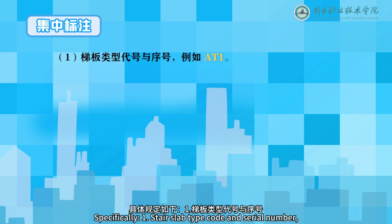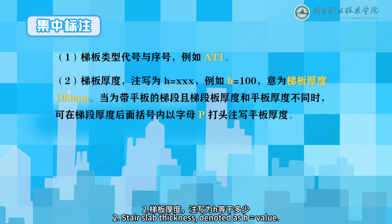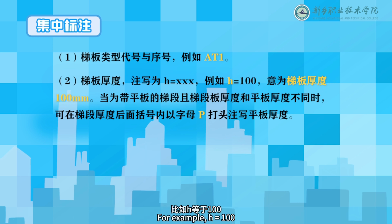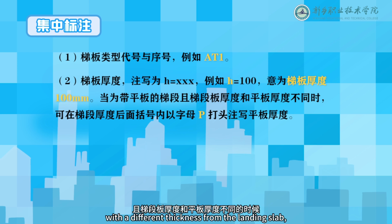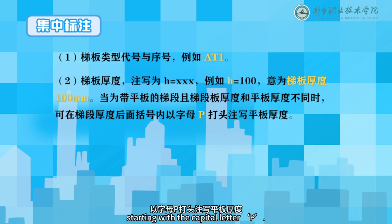Specifically, 1. Stair slab type code and serial number, such as at 1. 2. Stair slab thickness, denoted as H equals value. For example, H equals 100, indicates the slab thickness is 100 mm. If the stair section includes a slab with a different thickness from the landing slab, indicate the landing slab thickness in parentheses after the stair slab thickness, starting with the capital letter P.